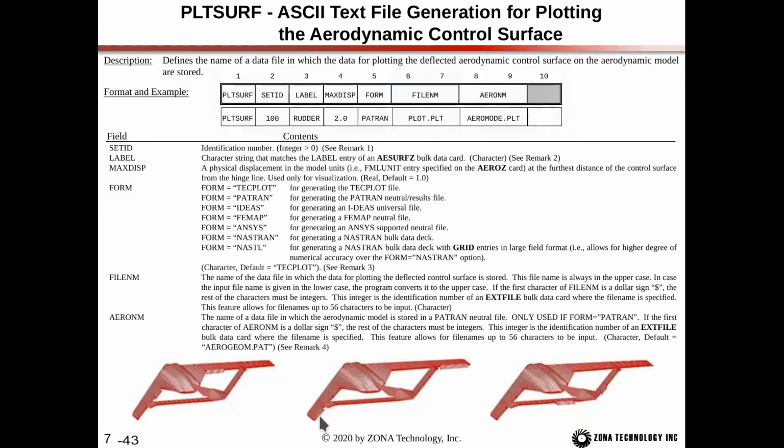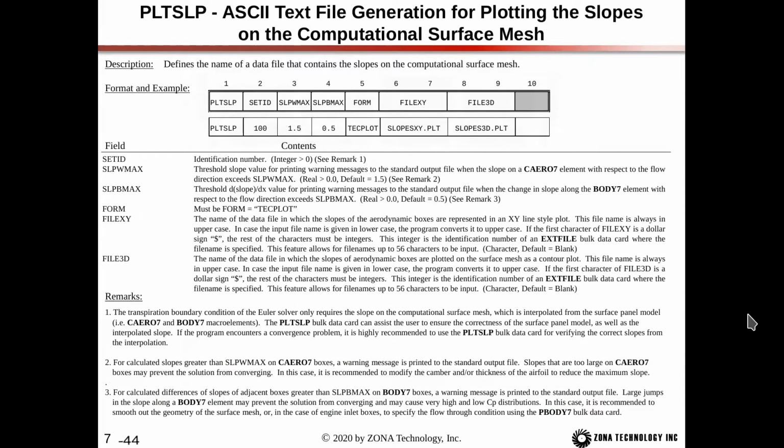Two, that your hinge line, you've defined it correctly and the sign of the hinge line is what you expect. Next, we have plot SLP, or plot slope. This generates a plot file for plotting the slopes of the computational surface mesh.